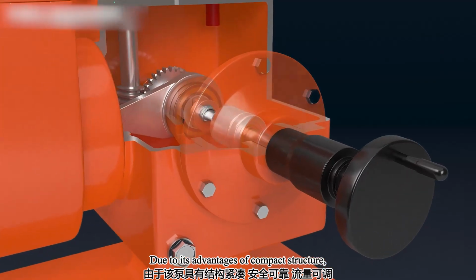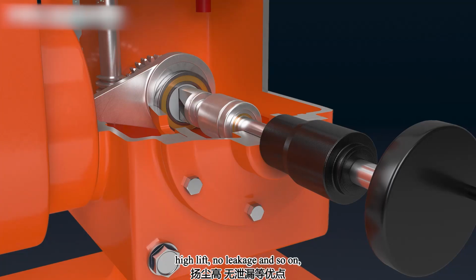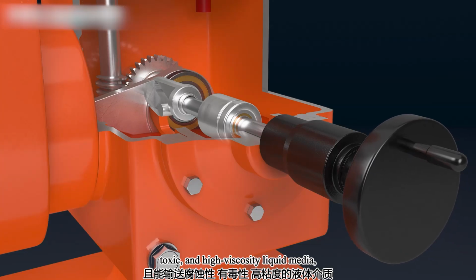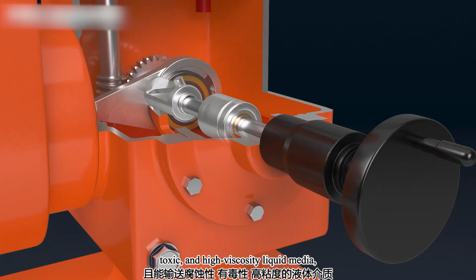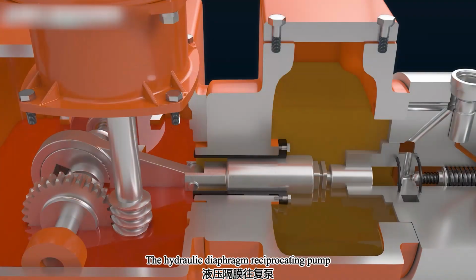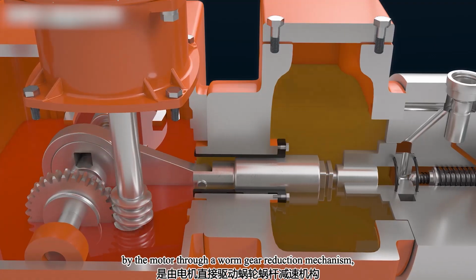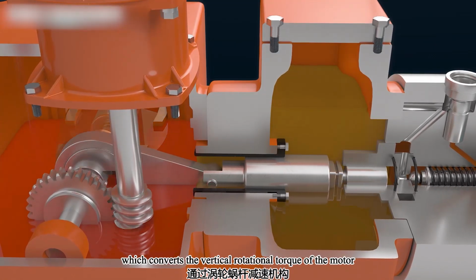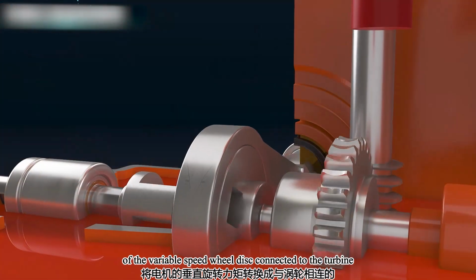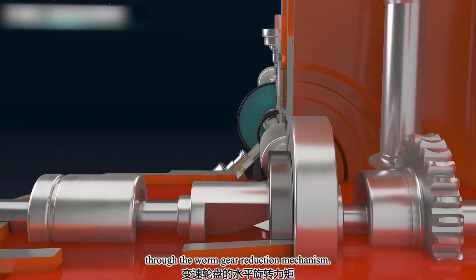Due to its advantages of compact structure, safety and reliability, adjustable flow rate, high lift, no leakage and so on, and the ability to transport corrosive, toxic, and high-viscosity liquid media, it is widely used in various chemical plants. The hydraulic diaphragm reciprocating pump is driven directly by the motor through a worm gear reduction mechanism, which converts the vertical rotational torque of the motor into the horizontal rotational torque of the variable speed wheel disc connected to the turbine through the worm gear reduction mechanism.